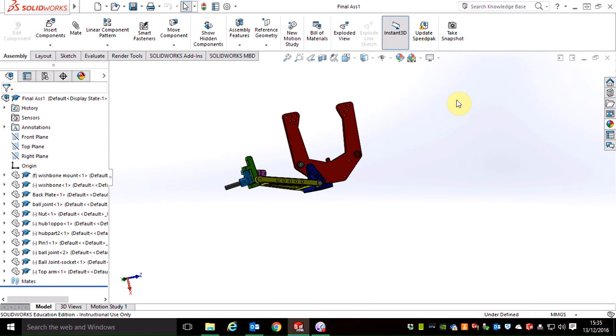Something similar that you might have seen before is if you save all your music in your iTunes player or your Windows Media Player, and you add it from your downloads folder where you've just got the music from, then one day you come around to sorting your computer out and you move all your music out your downloads folder into your music folder. So you open iTunes and you ask it to play something, it says can't play this, you need to locate it, because you need to tell that program where this file is, because iTunes doesn't save the music file, it just saves a path to find that music file on your hard drive. And this is exactly what SolidWorks does. It just saves a path on where to find that part on your hard drive.